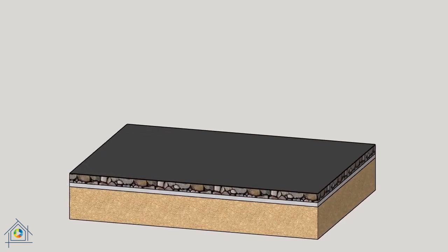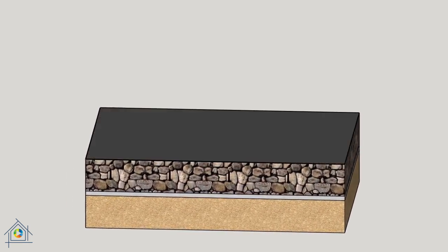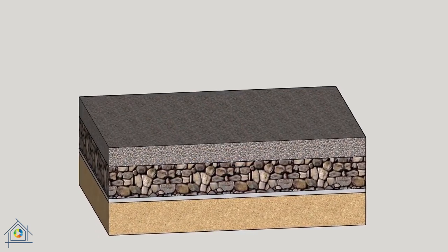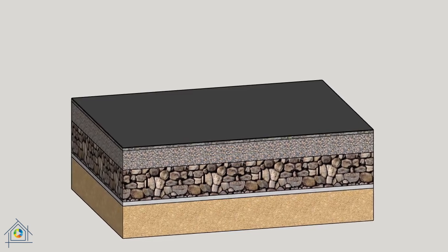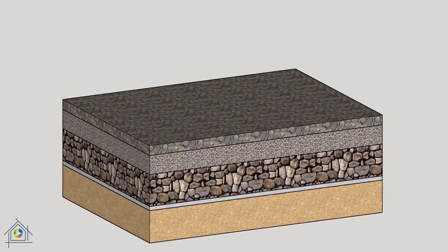To prevent soil moisture from transferring to higher levels, several layers of dry stone are used. First, large pieces of stone, then smaller pieces of stone with a thickness of 7 cm, and finally a gravel and sand mixture with a minimum thickness of 1 cm are poured into the flooring area. The total crushed stone layer is between 25 and 45 cm.